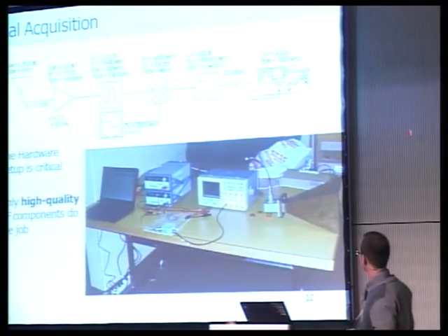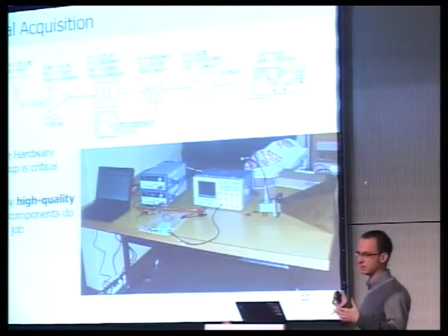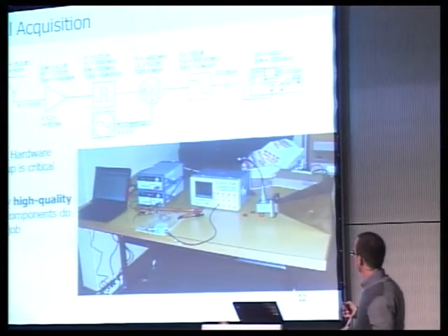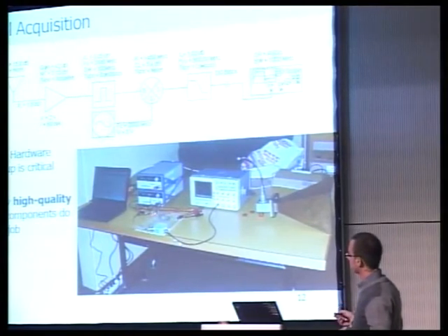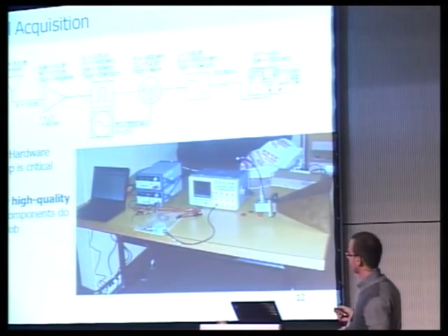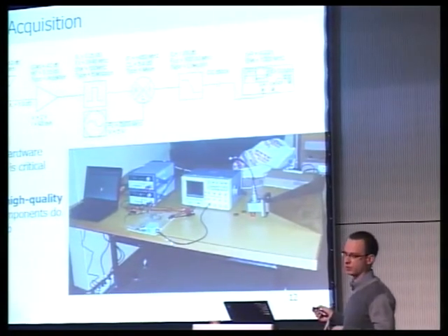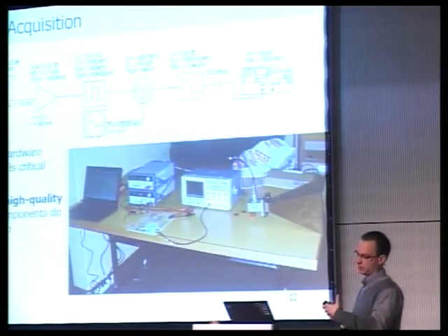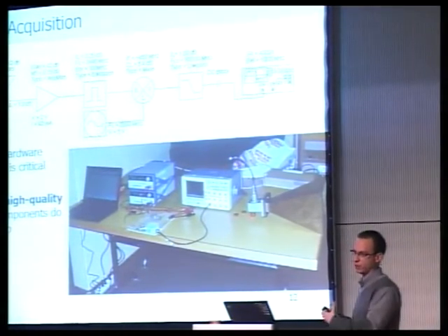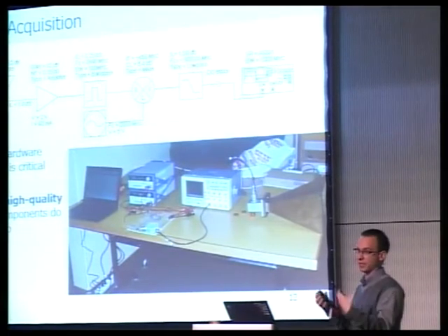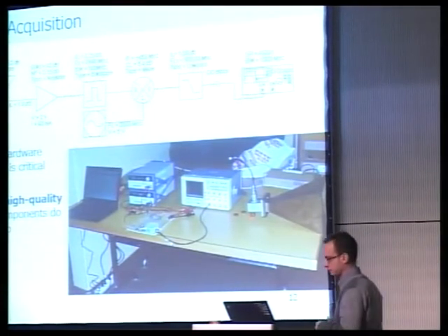The signals that all the devices emit are recorded from the antenna. They pass through all the filters and mixers, and are recorded on the oscilloscope and on our laptop. And then you are able to build reference features and test features and compare them to see, can we distinguish these devices?